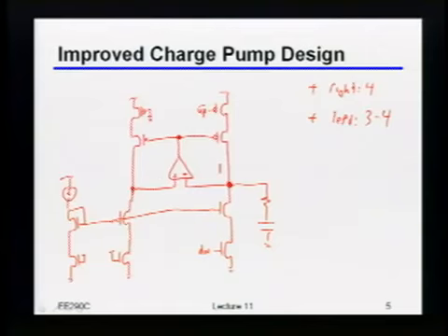But the nice thing is the loop filter drops that impedance, A. And B, the PLL also says, no, sorry, that has to be a fixed voltage, at DC at least. Okay? Does that make sense to everybody? So this is actually now starting to be a fairly common charge pump design. Because of some of the charge injection issues we talked about, you might even add some injection cancellation switches and things like that. But basically, this is indeed starting to be fairly realistic.